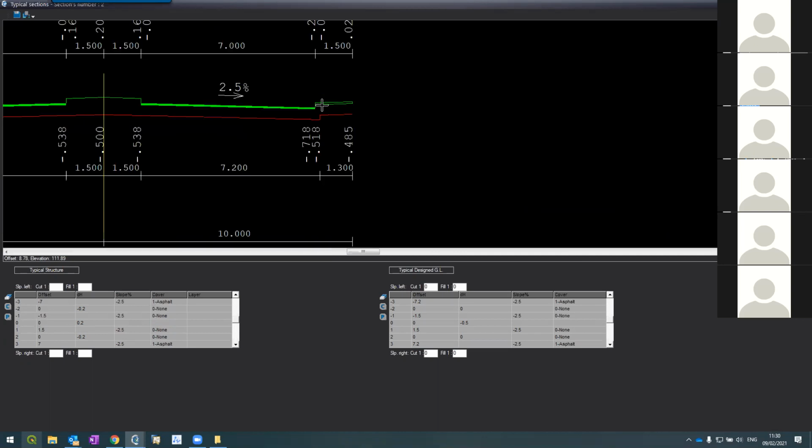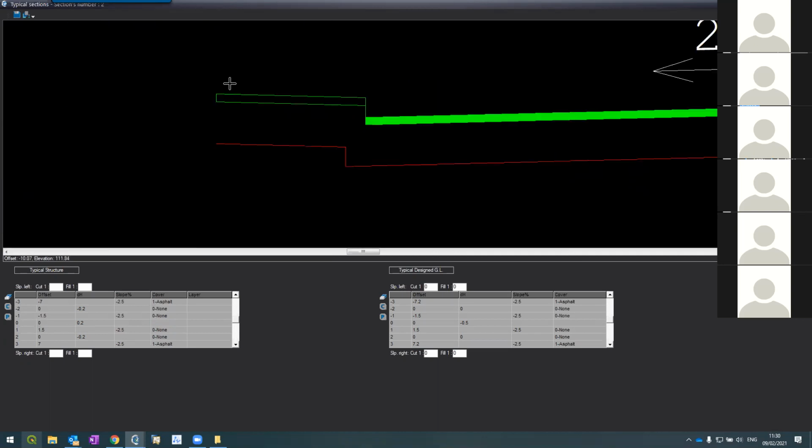Okay. But my structure level, actually the bedding below the path, below the sidewalk, is not 60 cm because I don't have subgrade. I have only sand here. No bitumen, nothing. So here this drop is not 20 cm. Let's say that the width here is 20 cm altogether, from here to here.